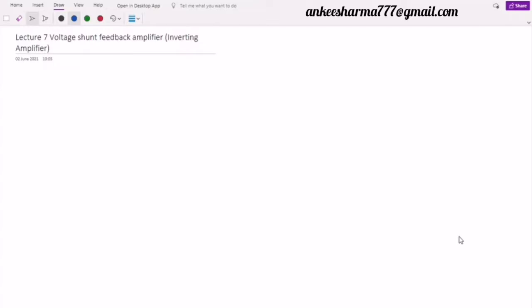Yes, good morning, class. In the last lecture, we discussed different feedback amplifier configurations. We have seen that there may be voltage series, voltage shunt, current series, and current shunt. Also, we discussed the voltage series feedback configuration, where we applied the input to the non-inverting terminal. We derived the values of gain with feedback, input resistance, and output resistance.